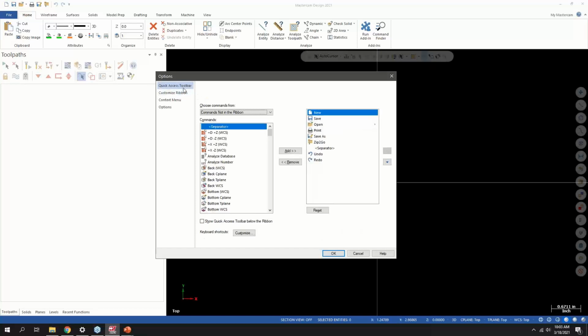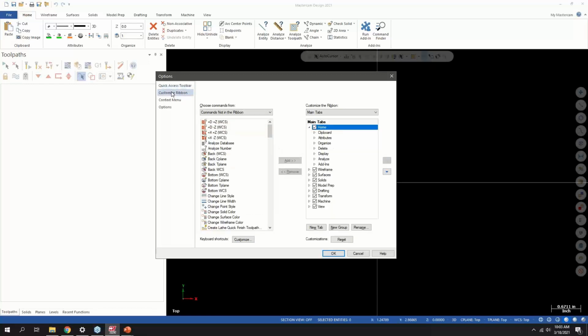So first you have your quick access toolbar. That's these icons at the very top left. Mine are default here, but you have undo, redo, save, print. But you can add really any function you want in Mastercam up to this bar, and then you can also show it below the ribbon. So I've had guys that have been really big fans of the X versions of Mastercam with the little tiny icons. If you wanted to, you could basically build the X interface via this method and show it below the ribbon bar and have all the little icons show up if you want.